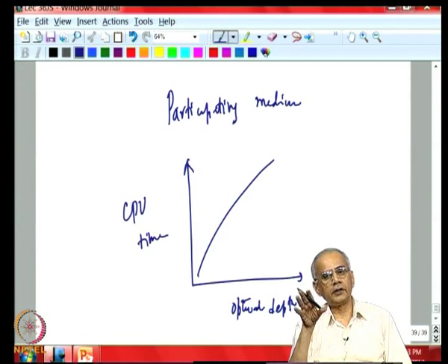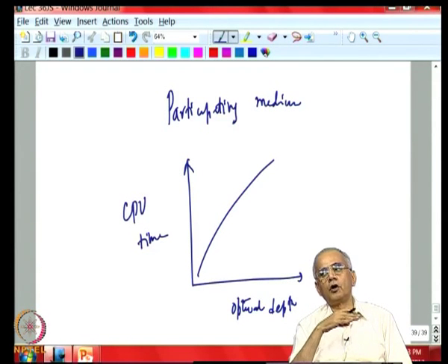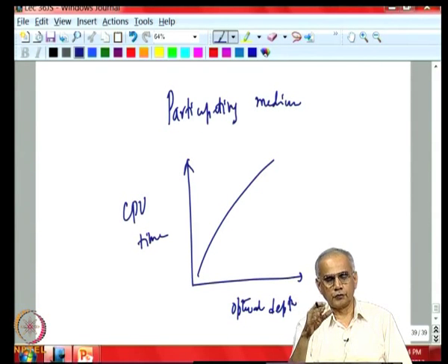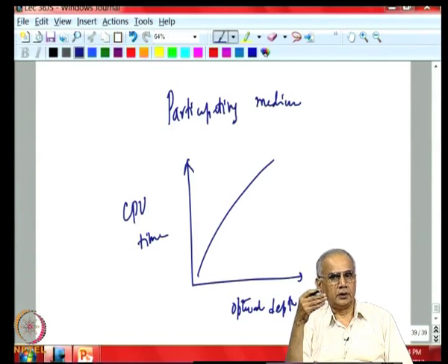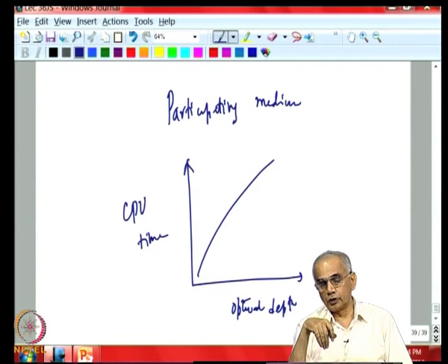If it is an optically thin medium, it is hardly absorbing or scattering. So, the number of events that you will see inside the enclosure will be small. Most of the photons will leave one wall and reach another wall without much change in direction or loss of photon.